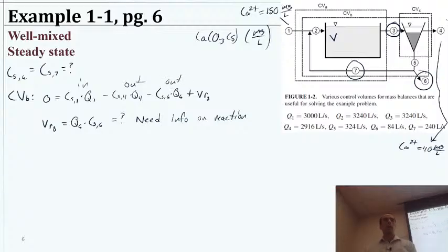But if you think about it, we were told explicitly that we are growing solids, so we need a reaction term within the reaction vessel. It also wouldn't make any sense to have 0 coming in, 0 going out here, and suddenly we have some going out here. We have to have a reaction to balance that. But given these two zeros, we notice that the C_S coming in, that term should go to 0, and the C_S going out the clarifier should also go to 0.